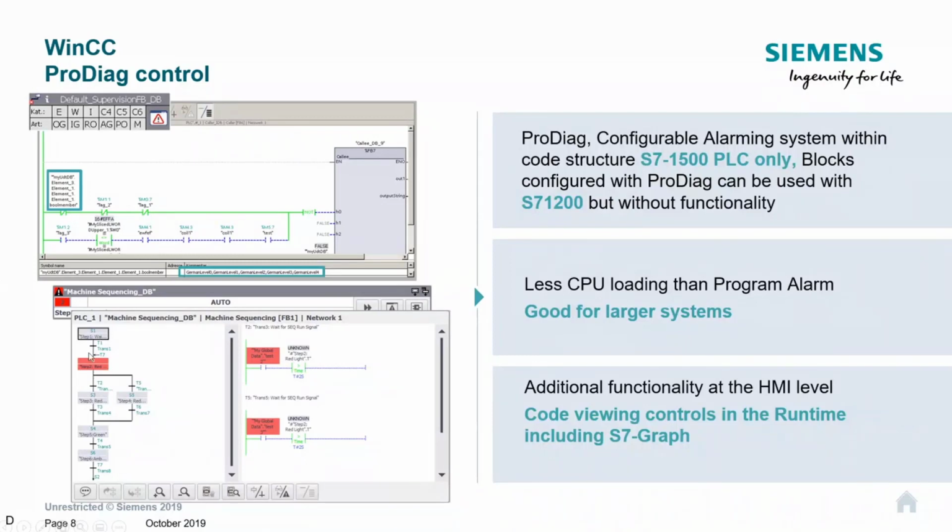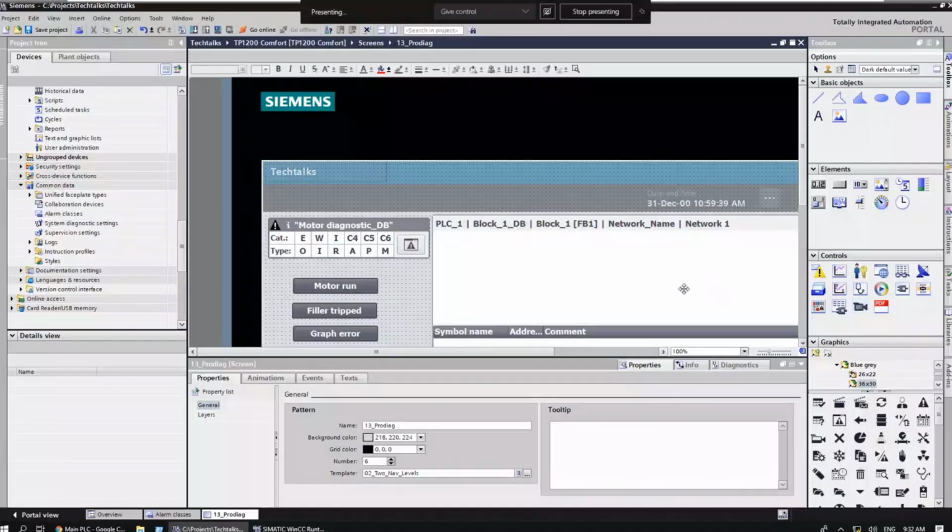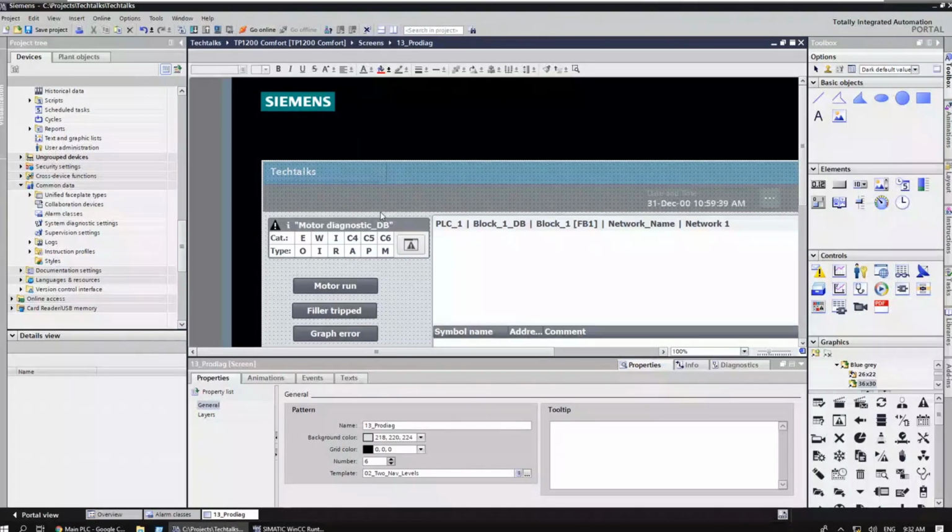Now, in this instance, this is what I've done. It's actually sat here waiting for an operator to make a decision on whether I want the orange light to come on or the orange light to flash. In this case, I just made a very, very simple traffic light system. Okay, and we can see here the detail of what the transition steps, which is here and here, is waiting for. We can see these highlighted, and we can see the step information there. Okay, so Dave's going to take you through this live in more detail and show you how to configure it all up.